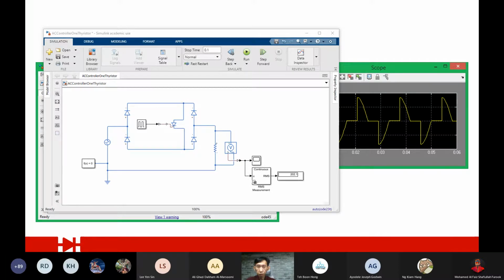You will notice the result may be slightly different compared to the one that uses two thyristors or a triac. That is simply because there are voltage drops across these 4 diodes. So it's about cost and performance.